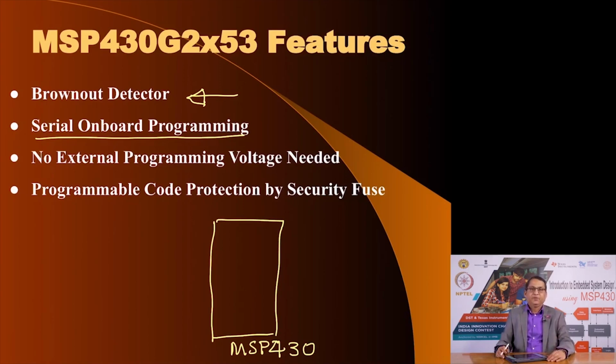You could utilize it. If you choose to use the in-application programming, that is programming with bootloader, then it uses the UART which MSP430 has, and in fact our MSP430 evaluation kit, which is the MSP430 lunchbox, uses this method. This allows you to program microcontrollers with very little external support, and we will show you a variety of ways of actually making your own evaluation kit. In case you do not have access to the lunchbox, we will show you how you can create your own